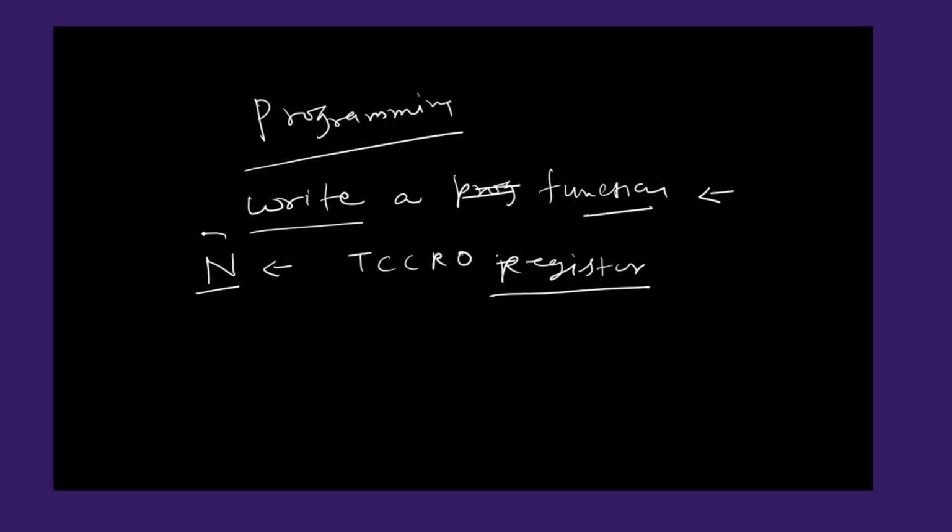Once we load the proper prescaler, the timer starts counting pulses. By default, when you start the microcontroller, the timer counter will be in the disabled mode, or it will not be counting the pulses.